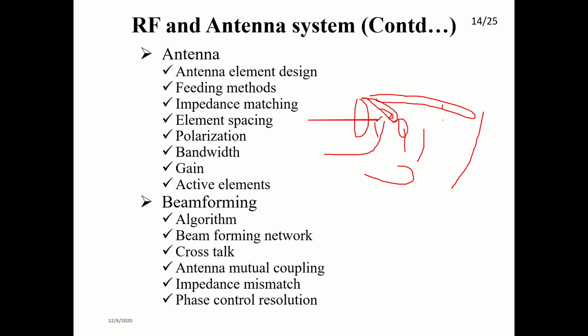Bringing impedance matching between your amplifier and the antenna is a very tough task. It may be a 1 month effort or 6 months effort for an expert engineer in this field. Once you design the antenna separately, bringing in impedance matching is very, very difficult. That's why people are proposing integrated antennas, along with the amplifiers and everything. They will design the whole chain, antenna also, so that you need not work on impedance matching separately.